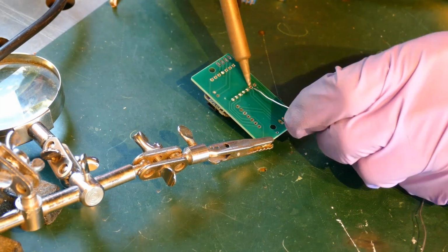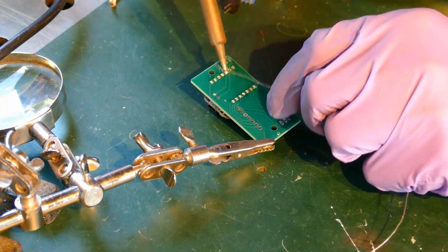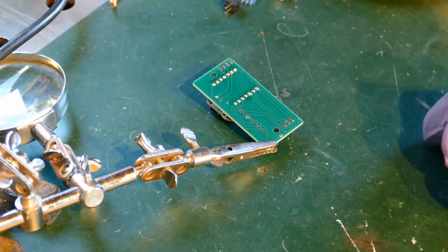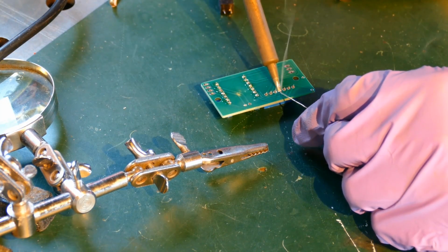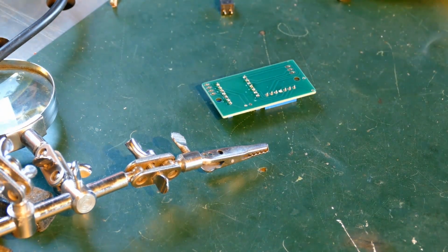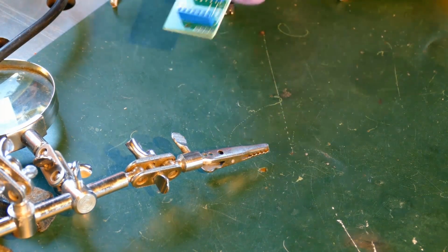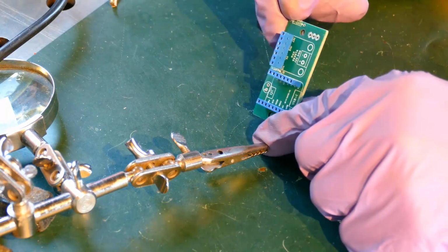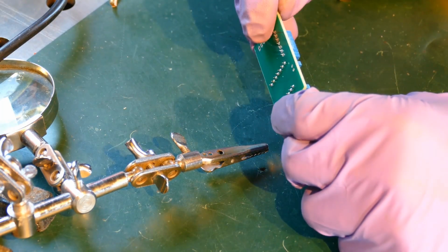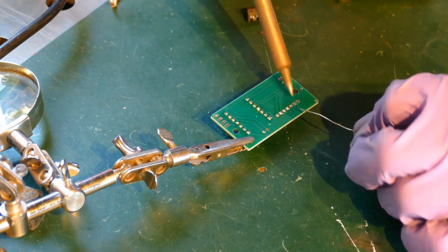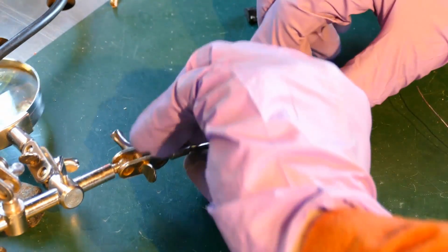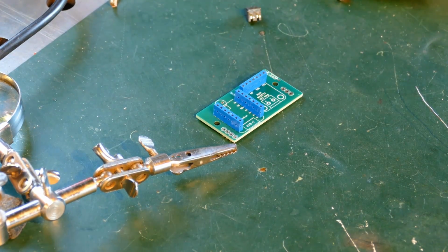I'll solder 7-pin female socket headers to hold both the QT Py and the I2S Amp. This way the boards can easily be removed, which is very helpful for debugging. One tip for when you're soldering headers is just to do the middle one first, and then check afterwards that everything is seated properly. If not, it's much easier to fix now than when all the pins are soldered. And once you have one pin soldered, it can be clamped in any position without the components falling out.